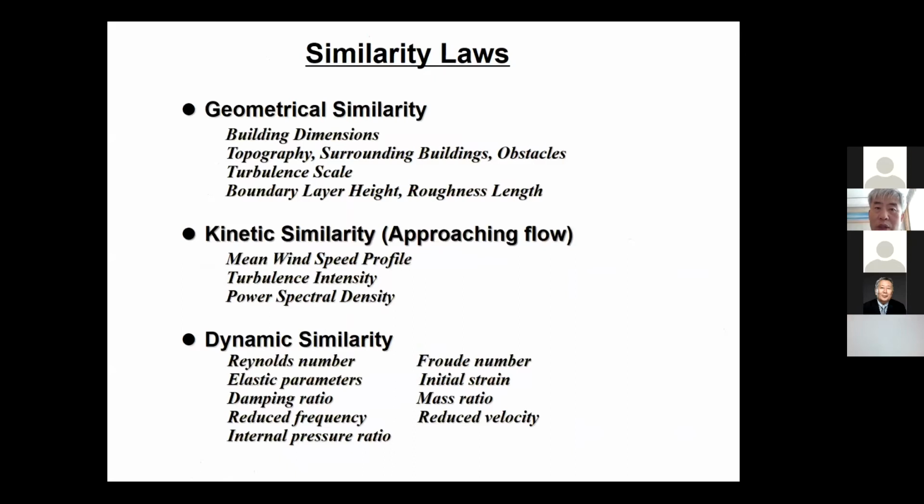But when we do a wind tunnel test, of course we have to consider similarity, because we use a small scale model in the wind tunnel. We have to consider geometrical similarity, a lot of it. We have to consider the similarity of the building itself, and also the geometric similarity between the atmosphere and the flow inside the wind tunnel. And also we have to consider the approaching flow.